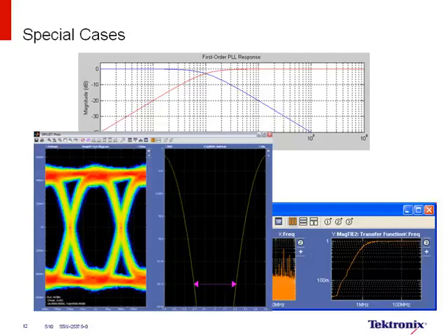So if you send a clock, for example, through a PLL, guess what? It rejects the high frequency jitter. So that's one example where the CDR has the ability to high pass, track, and reject low frequency jitter, and if you send a clock to a PLL, you low pass, or reject, high frequency jitter. Hopefully that answers the question about the difference between a low pass and a high pass jitter transfer function.